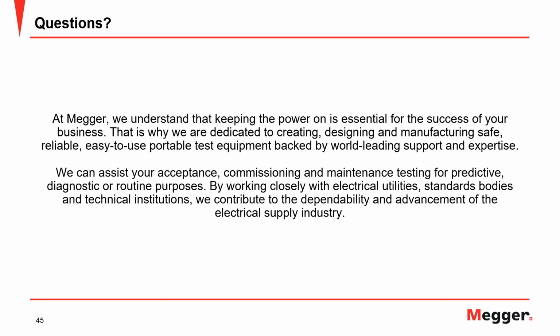So with the DFR that Diego covered in this presentation, we are looking at the varying values of power factor that we get with the changing frequency of the voltage that we apply across the bushing C1. The reason why this happens is because of polarization.